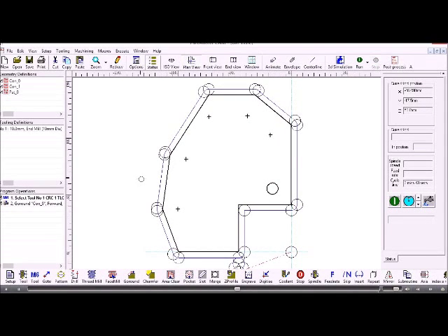So that's showing me the tool going from the datum position there. The dotted red line is a rapid motion, the arc approach there, machines all the way around, and then the arc runoff. If we want to view the tool in different ways and the graphics in different ways, we use the toolbar at the top here.